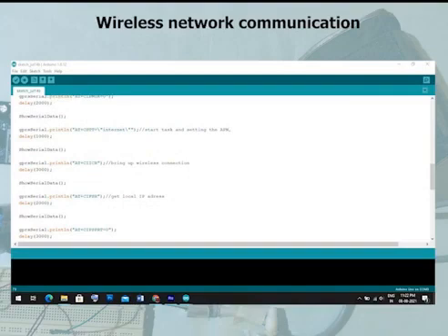In our case, we are using an IDEA SIM card, thus the APN for IDEA is called Internet. Next, we set the network to obtain the IP address, and finally we have inserted the API write key of ThingSpeak so that the data coming from the MCU gets displayed on the cloud server.